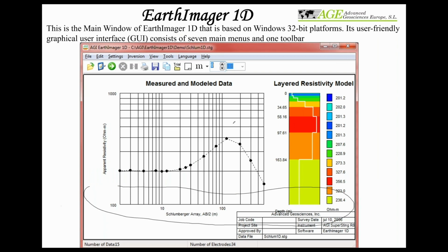Okay, typically this is a vertical electric sounding data. What you have here is apparent resistivities in ohm-meters, and this is a typical Schlumberger vertical electric sounding. Half of the electrode spacing of Schlumberger, the current electrode spacing, is typically how we try to plot our data. If you have a Wenner, you have Wenner over here. For vertical sounding, you typically use Wenner and Schlumberger, but you can also use other array types. I will show you later with our software that you can do that as well.